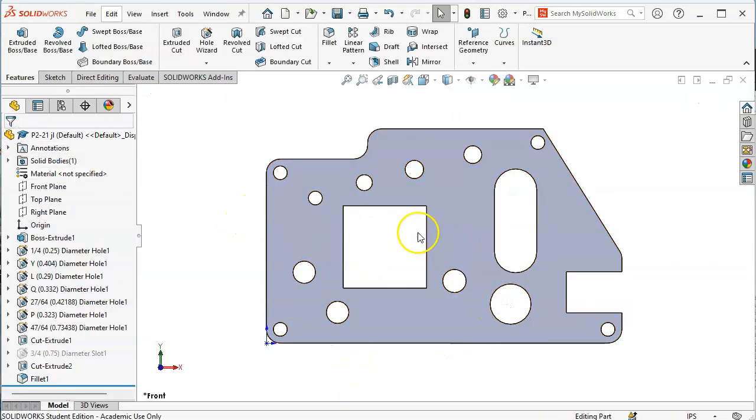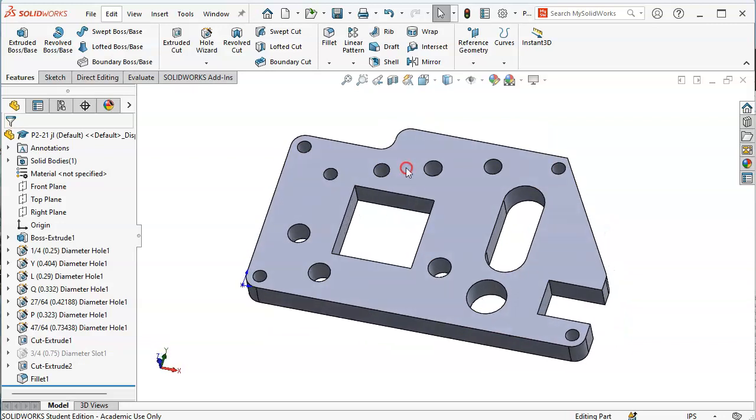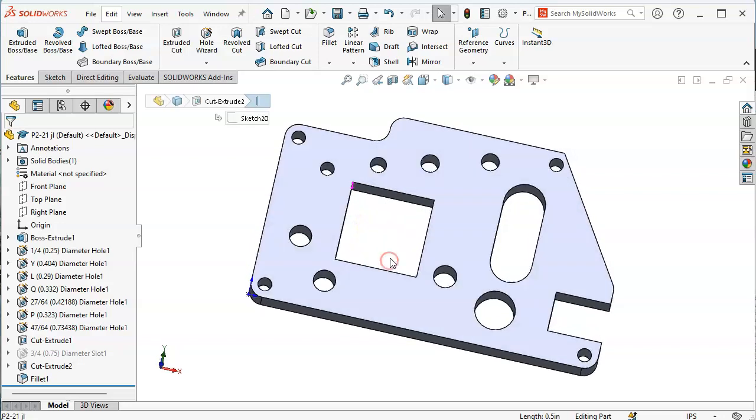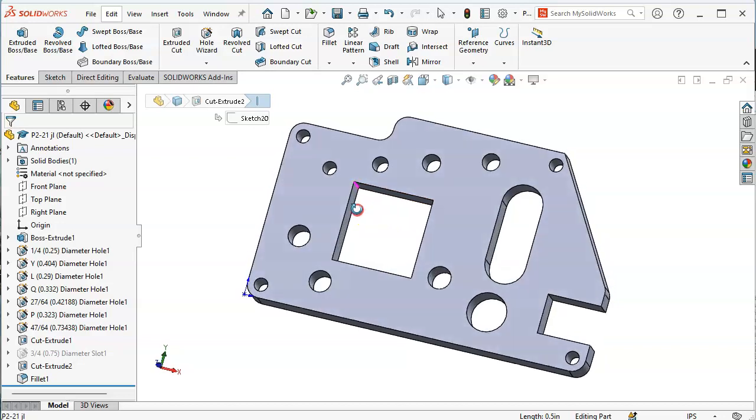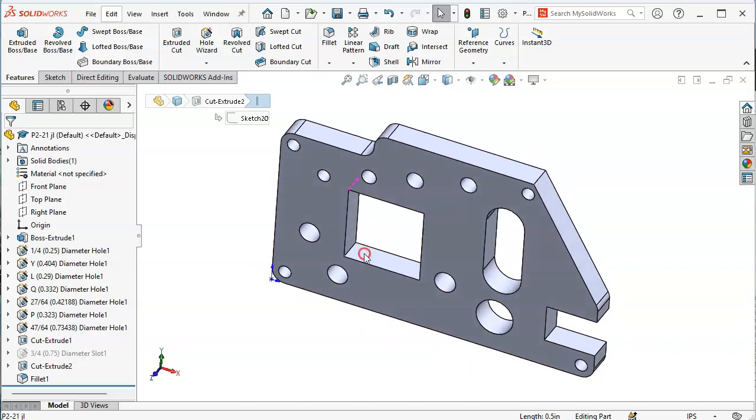One of the considerations is that in our manufacturing process, round tools do not cut square holes. So at the very least, I would want maybe an 1/8 inch. For a 1/2 inch thick part, I would like to have a 1/4 inch diameter tool, which gives me a 1/8 inch or 0.125 radius. So I'm just going to drop those in as a what if.